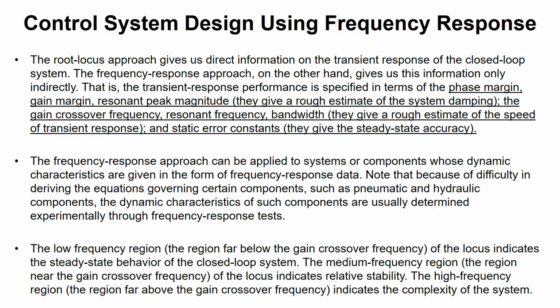But I told you that you can consider the system to be a black box, send in harmonics with known amplitude and phase, and then get the output of the system and measure the amplitude and the phase of the output and compare it against the input. And then you can get the magnitude and phase plots like the Bode plot without even knowing what's going on in the system. So you can get these frequency plots without even knowing the actual mathematical model of the system, and that's a big advantage.